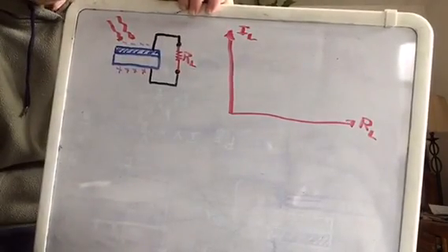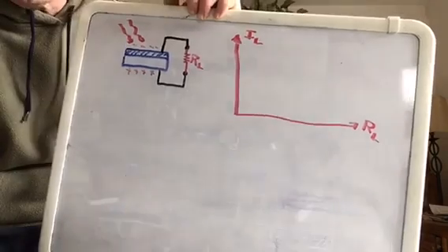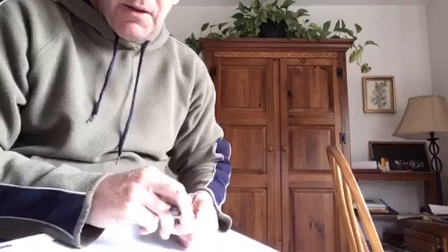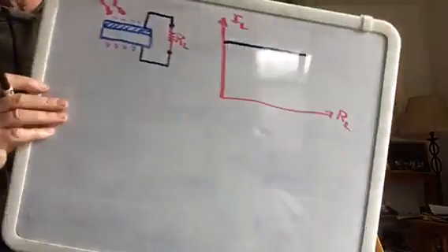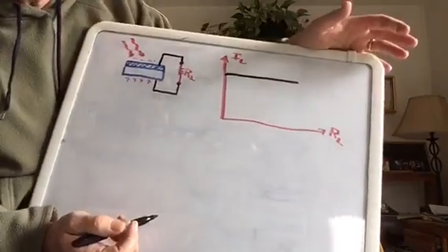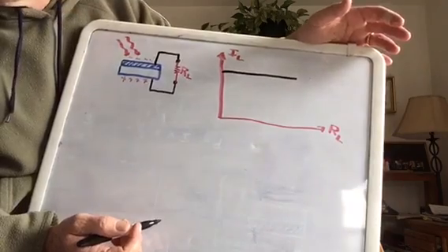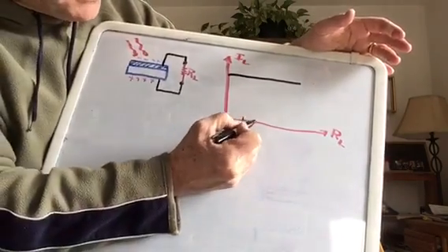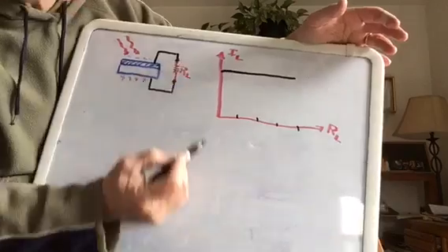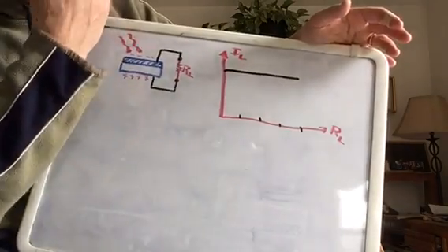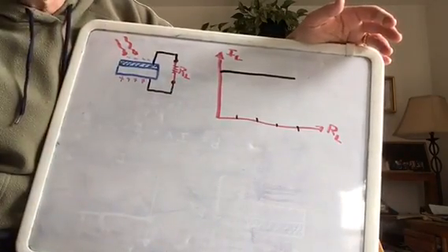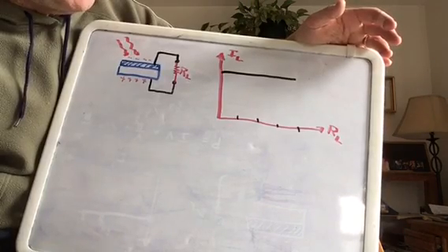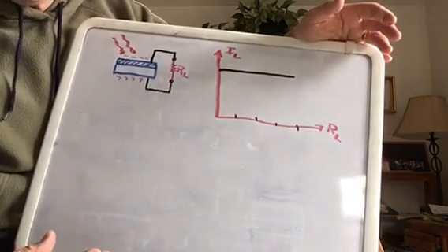Okay, so a solar cell is a lot different, all right? What we want to be able to think is, what does it mean to say that a PV cell, or a PV generator, which is the blue thing, is a constant current producer? Well, that's what the graph essentially would look like: no matter what the resistance that's hooked up, we end up getting the same current going on. And a little bit later on, we're going to try to do a demonstration to show that that is basically true. Okay, so why would that be?